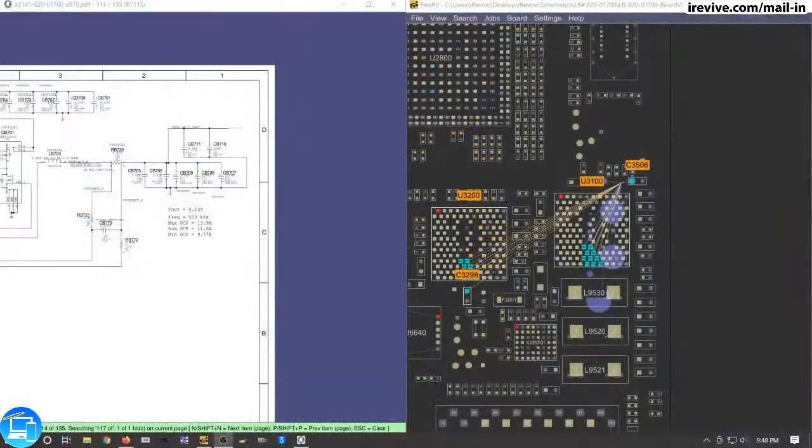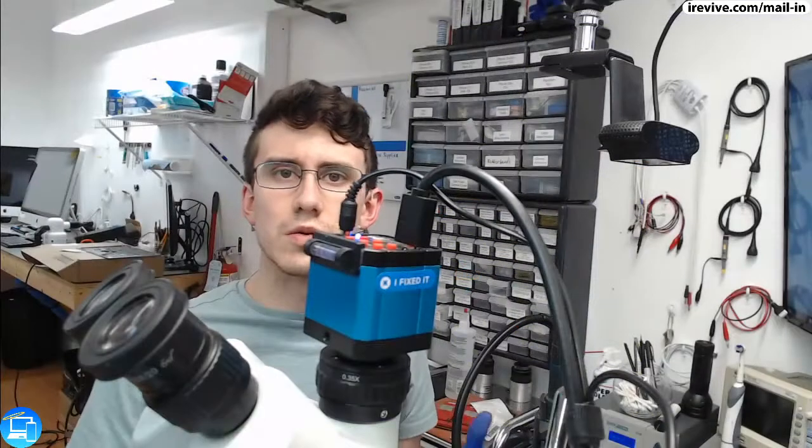That's why I wanted to do this specific stream. The USB-C ammeter is reading 20 volts at 0.2 amps for probably about 5 seconds, then it goes to 0 amps. Now, from my previous repairs, whenever I had that, it usually meant there was a short somewhere on a main power rail. Now, I know since this one is a T2 chip, it can also have a corrupted T2 chip and go into DFU mode as well.